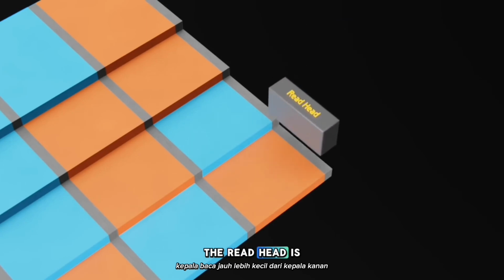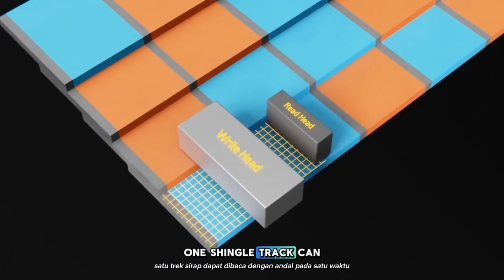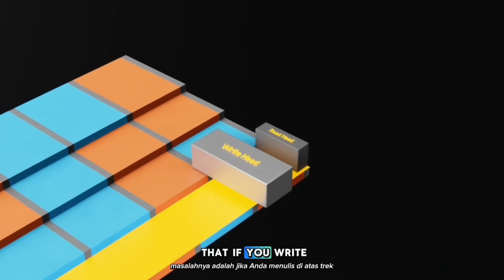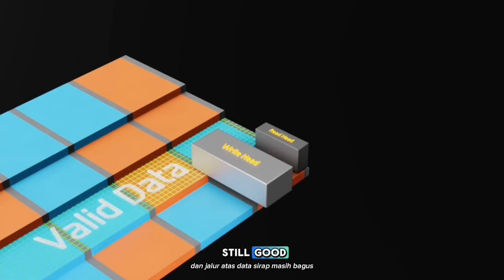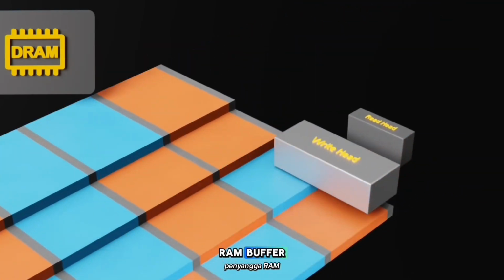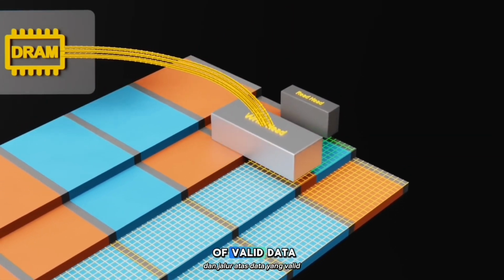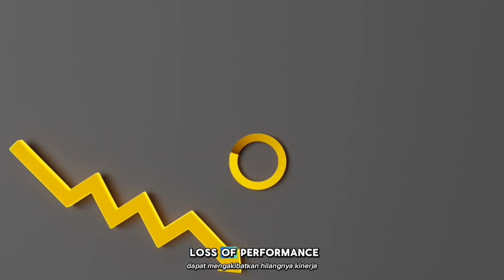Note that the red hat is much smaller than the white hat, and as a result, one single track can be reliably read at a time. The issue, however, is that if you were over a track and the upper track of shingled data is still good or valid data, the drive will first have to read and store the valid data in the DRAM buffer and write both the lower track of new data and the upper track of valid data. And as a result, the buffering and the extra read and write step can result in a loss of performance.